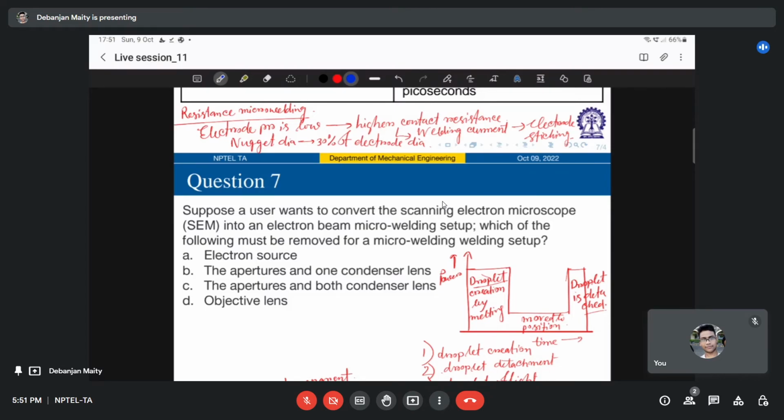And when these electrons scan the surface of the specimen, electrons are scattered, right? And those secondary electrons that are slowed down on the impact of hitting the surface are collected by a detector, and these secondary electrons create the magnified image of the specimen, and it can thereby illustrate the morphology and topology of the specimen.